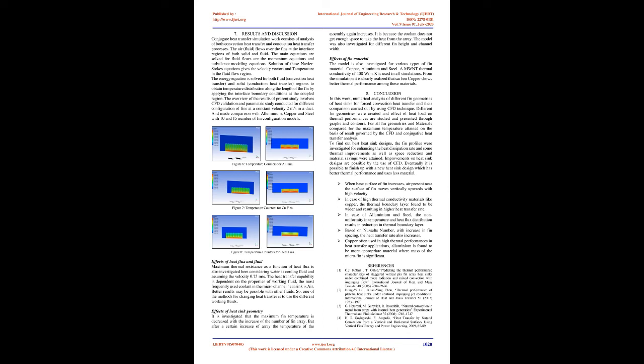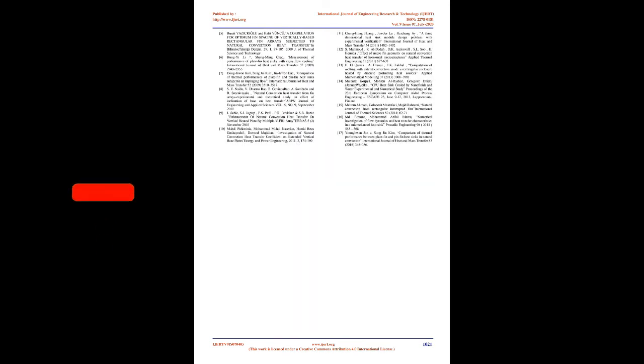The reasons for the comparatively coarse discretization for the z direction are that, with the exception of the inlet region, the temperature gradients are small compared to the gradients occurring in other directions, and the CPU time as well as the memory storage required increases dramatically as the number of grid nodes is increased. Furthermore, comparison with standard numerical results indicates that the finer the mesh size, the higher the numerical accuracy.